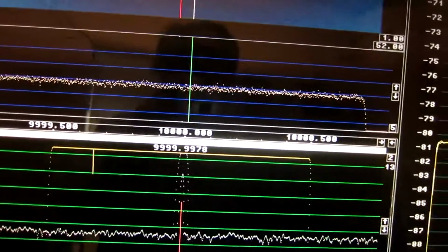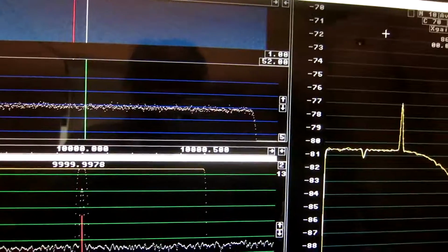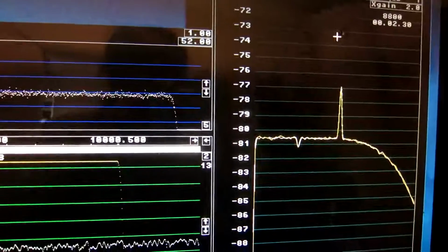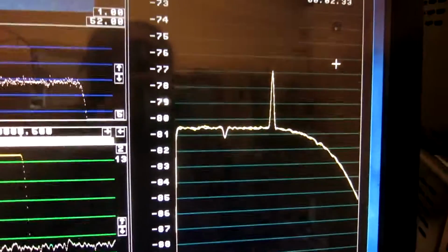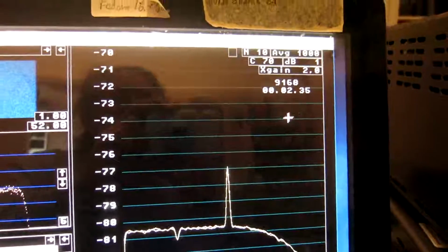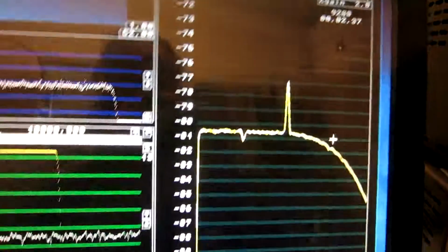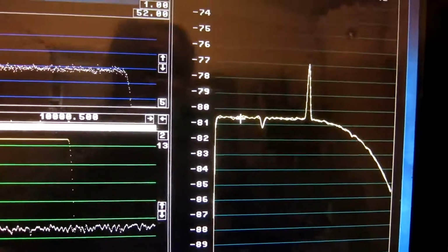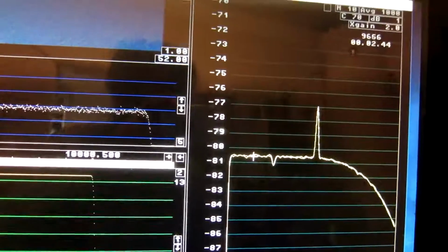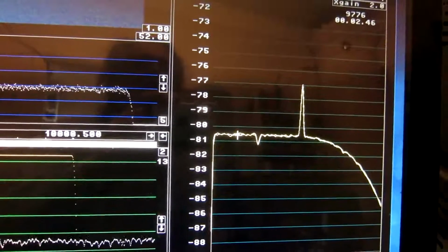I have set Linrad now for correlation spectra mode 2, and here is the signal analyzer graph after 2.5 minutes. I see 80.5 approximately. That's wrong by 2 decibels.